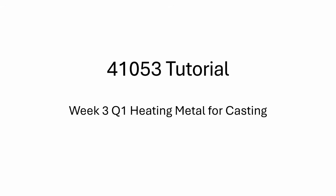I can start with the first question, and it's going to be about the heating of the metal for the casting. As you learned from the topic itself, in this week we are going to discuss the casting processes. And in the casting processes, the main thing is that the metal should be changed from the solid state to the liquid state. Here we are going to learn about how to calculate the amount of the heat required to make the metal not only melt, but also be raised to the pouring temperature.